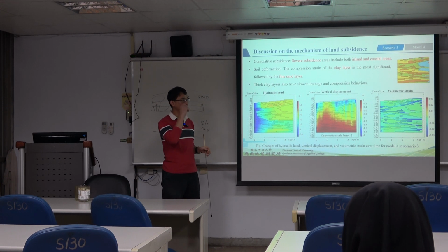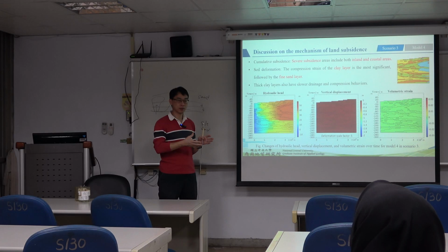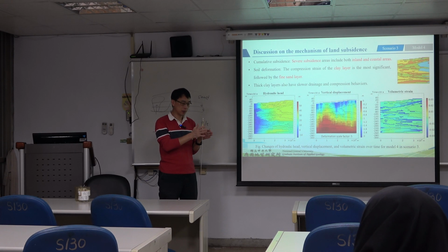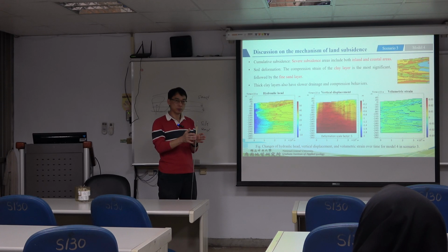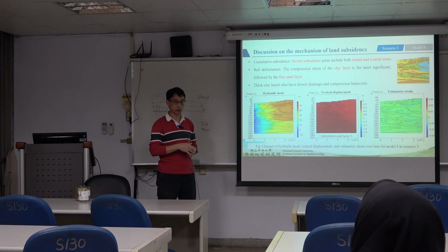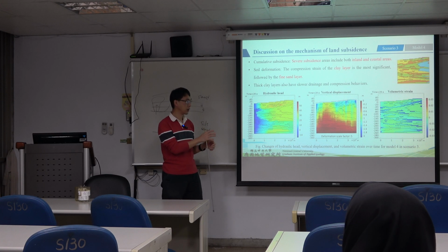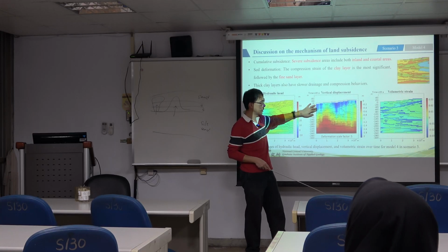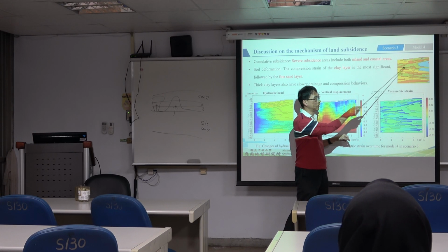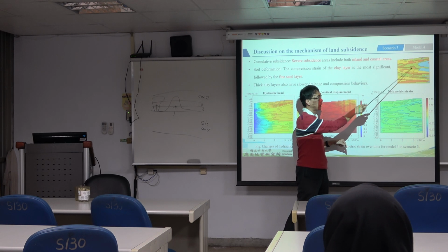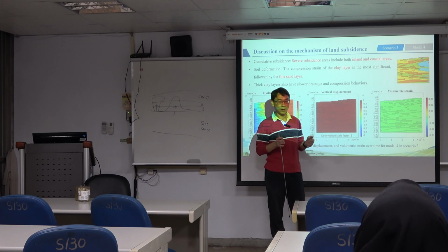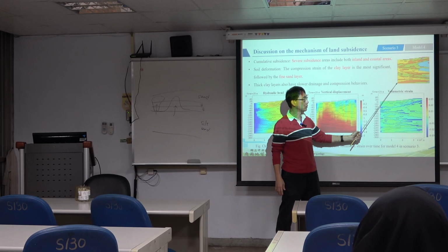We see that in this area, in the past, the subsidence mainly occurred in the coastal area, and after that, it propagated to the central. So these kinds of models look like they can represent these behaviors. We see the subsidence in the coast first because the clay is relatively thin. You can see that the clay is very thin here, but in this area it becomes very thick. So it takes much longer to dissipate. So the subsidence occurred in the coastal area first.